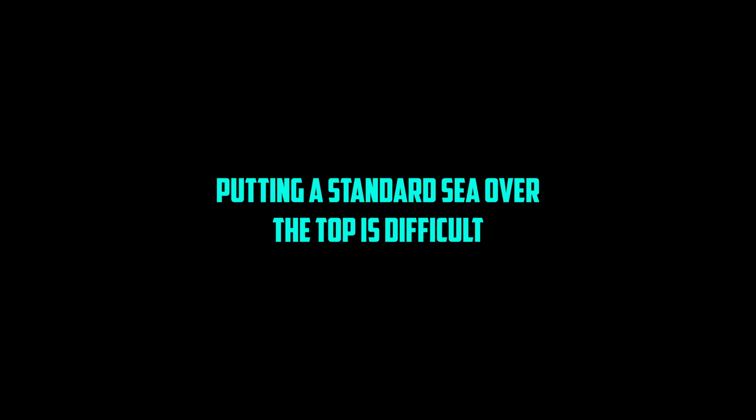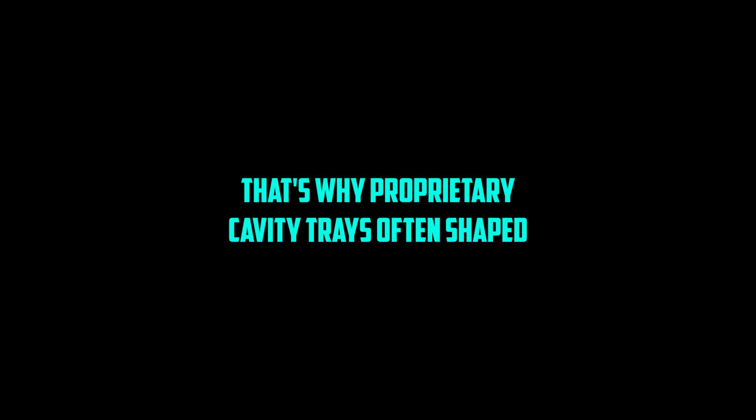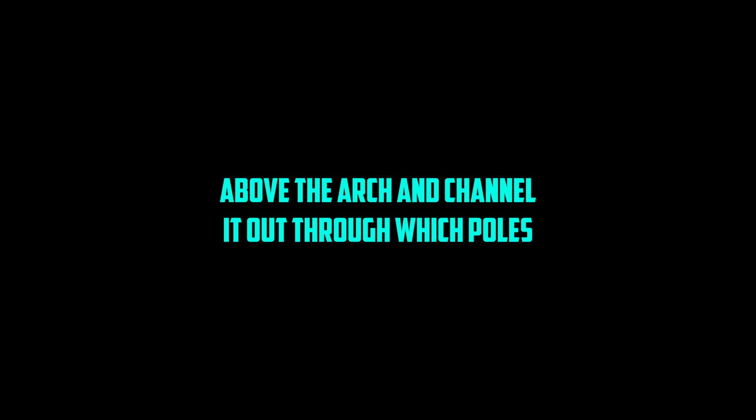Arch construction looks tricky for damp proofing. It is. An arch supports itself once built, usually over a temporary center. Putting a standard DPC over the top is difficult because water running down the cavity can bypass it. That's why proprietary cavity trays, often shaped metal or plastic, are used to catch water within the cavity above the arch and channel it out through weep holes.